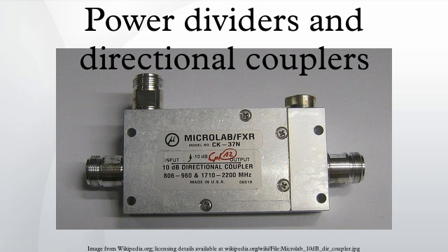Resistive T. A simple T circuit of resistors can be used as a power divider as shown in Figure 18. This circuit can also be implemented as a delta circuit by applying the Y-Δ transform. The delta form uses resistors that are equal to the system impedance. This can be advantageous because precision resistors of the value of the system impedance are always available for most system nominal impedances. The T circuit has the benefits of simplicity, low cost, and intrinsically wide bandwidth.